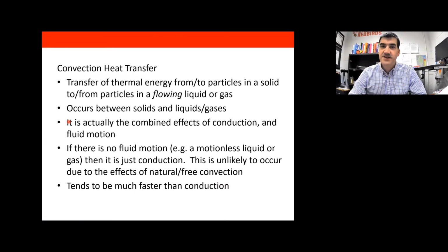All right, convection heat transfer. Quick review. We talked about this about a week ago, but a quick review of what convection is. It's the transfer of thermal energy from a solid surface to a fluid flowing over the top of it, or it could be flowing underneath it as well, or vice versa. So we've got heat flowing from a solid to a moving fluid, or from a moving fluid to a solid. So it's between a solid and a fluid, and the fluid has to be moving. If the fluid is not moving, then we've just got conduction between the solid and the fluid.